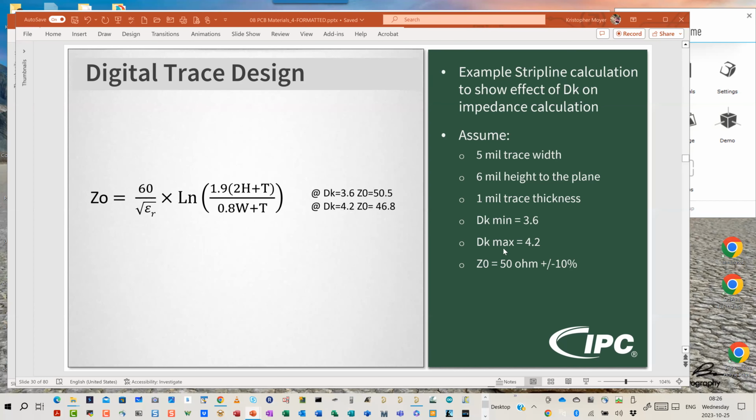So yes, you can absolutely play with dielectric thickness and trace width, but there's a caveat to dielectric thickness, and we will see this when we get to signal integrity. The thicker you make the spacing between the trace and the return plane, the larger the field loop areas for the E field in the EM wave, which means the larger the H field or magnetic field, which means the greater amount of crosstalk and inductive cross coupling between the aggressor nets and the victim nets for crosstalk analysis.